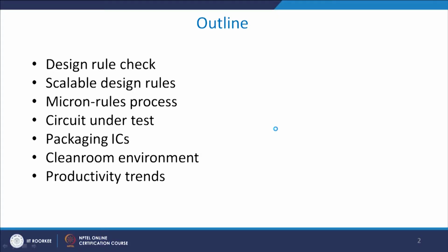So, I will give you certain design rule checks, also known as DRC. Once your design has been done on a simulation platform, your layout has been done, you need to check, for example, whether the width of the contact which you have drawn is as per the requirement of the fabrication facility. It might be true that a fabrication house can only make a contact which is, in very layman language, 1 millimeter by 1 millimeter, and you had made 2 millimeter by 2 millimeter. So, it will be rejected once your design actually goes to the fab house.